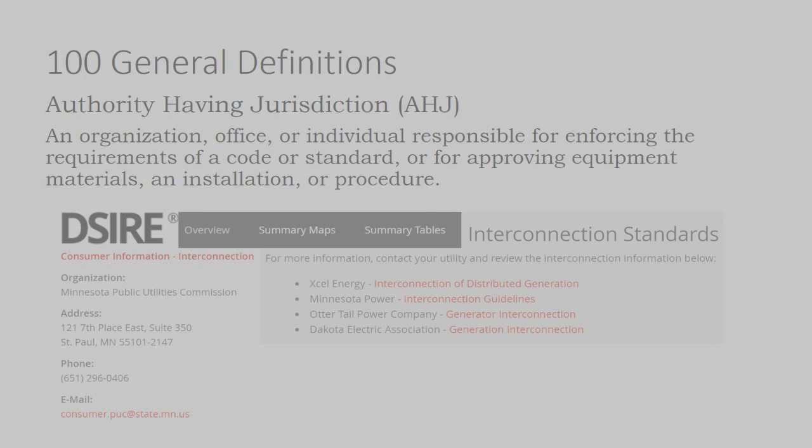Remember, National Electric Code is a private industry standard that is not designed to be a design manual. And so your local authorities have complete power to go beyond electric code in terms of having additional requirements. What's very common is that your local authority will want to have a disconnect switch on the outside of the building that is very clear and straightforward and easy to see from a distance.